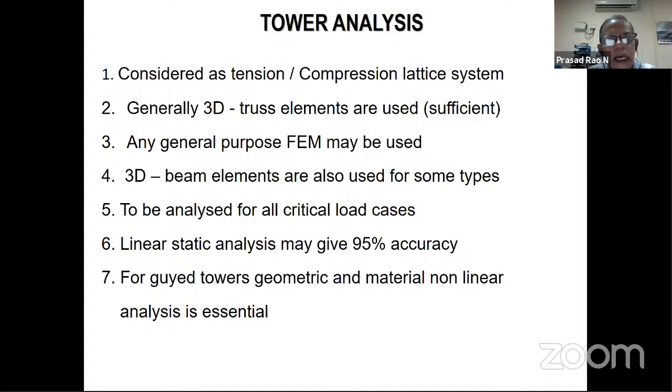For guyed towers, geometric and material nonlinearity is involved because the guy is a nonlinear element, it's a cable element. So we have to definitely go for nonlinear static analysis. So this is the analysis part.